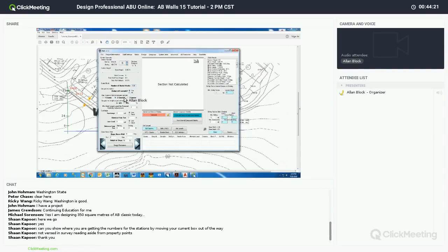Below that, also based on best practices, our course spacing is set to 2 courses. So you have 2 courses of block between each layer of grid. That's based off of a full seismic testing that we had done in the early 2000s. So if you ever want to see that, we do have that option. We can share that testing with you as well. You can go 3 course spacing if you so choose, but we do recommend sticking with the 2 course spacing per best practices.